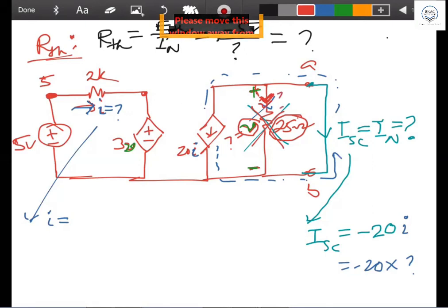0. If it is 0 ampere current, what will be V equal to? Ohm's law. Hey, we forgot Ohm's law. V would be 0. 25 ohm is the resistance. Current is 0 ampere. Voltage will be I into R. I is 0, R is 25. What is the answer then? 0. You understand it? The voltage across 25 ohm resistor will be 0 volt.